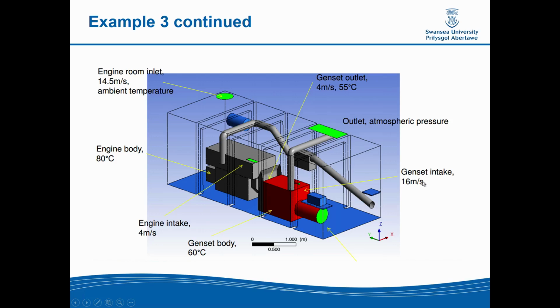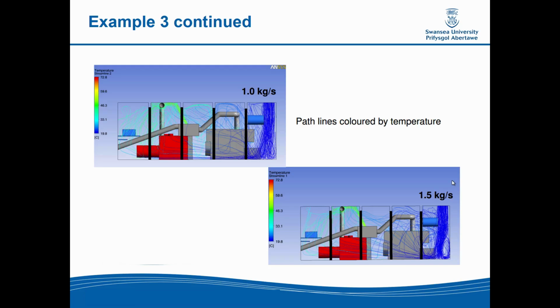I was actually quite proud of this one, because I was actually in that engine room out to sea, locating thermocouples on all the engines, because of course I said, you can't have a model unless you validate it. So he said, yeah, off you go. So quite a rough sea, stuck in the engine room with quite a high temperature, lots of fumes, and sticking thermocouples and infrared cameras all over it. But we were able to come up with some configurations which allowed them to choose how they would align the engines and the intakes in such a way that the temperature would be optimal for a given atmospheric condition.